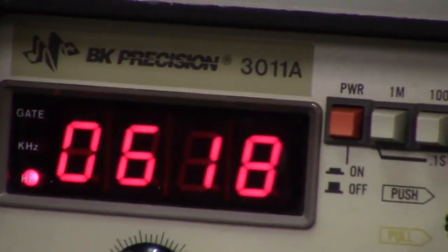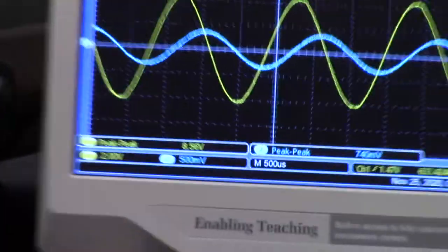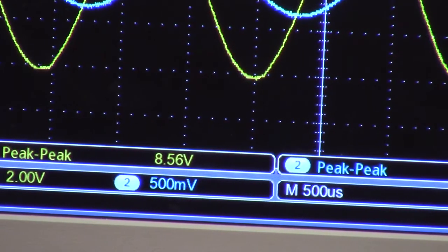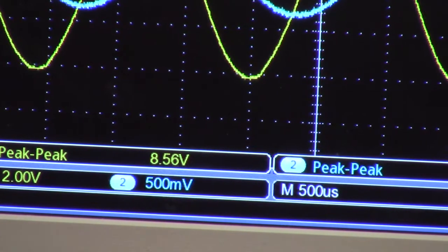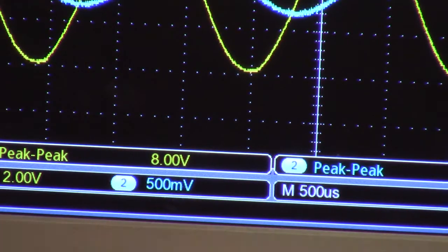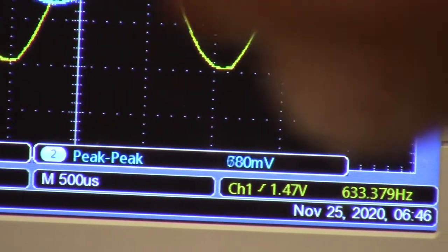That wasn't much of a change, and we are getting quite a bit off of resonance, so I think we can make some bigger changes. I was trying to keep it around 20, but I got 30 there and then another 20, so actually, that's about a 25 there. Okay, so anyways, 634 is the frequency. I'll do that one, and again, I'm going to have to adjust the voltage and give it a chance to measure. Okay, 8 volts, and then that is 700 milli. Okay.